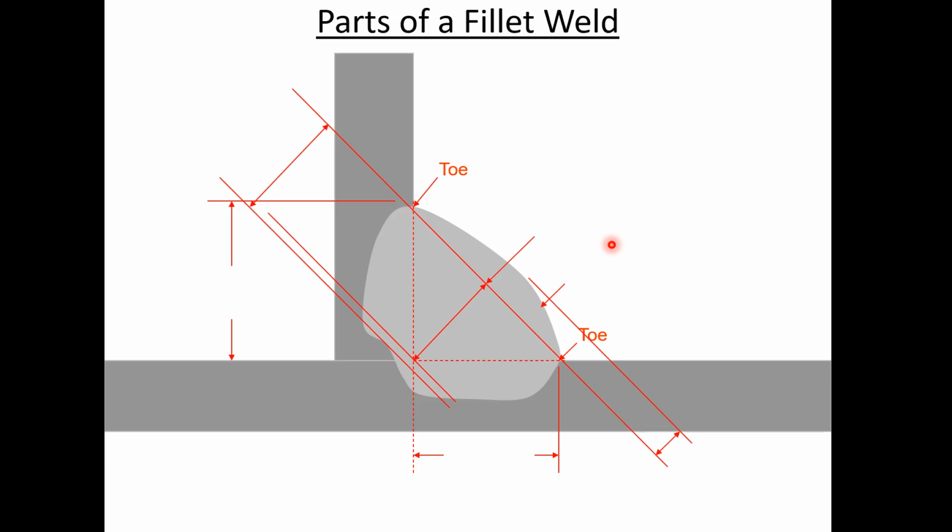How much of a bump is on this weld and how the material flows into the other one tells me a lot about how much penetration we actually have. Because we actually need, as I was talking about before, this homogeneous mixture in this area to give the weld the extra strength that it needs. Not to mention, it gives it more fortitude. The deeper we can go into the base metal, to a certain extent, the more strength we'll end up having.